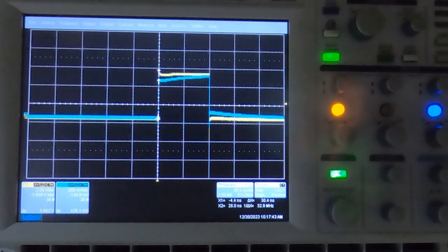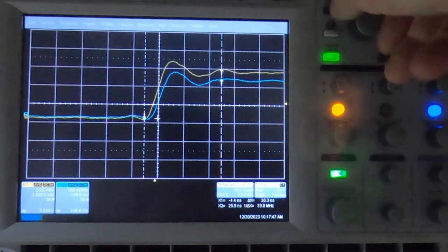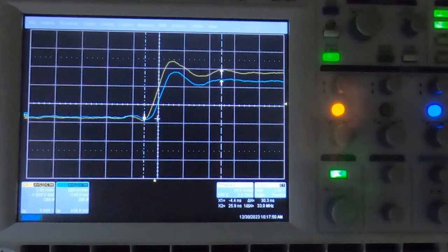So a few nanoseconds doesn't really matter. It does matter if you're working on very high frequency circuits. About 90% of my commercial designs have included RF systems, and when you're talking about hundreds of megahertz, then yes, a few nanoseconds makes a big difference. That's why I have this scope in the first place.